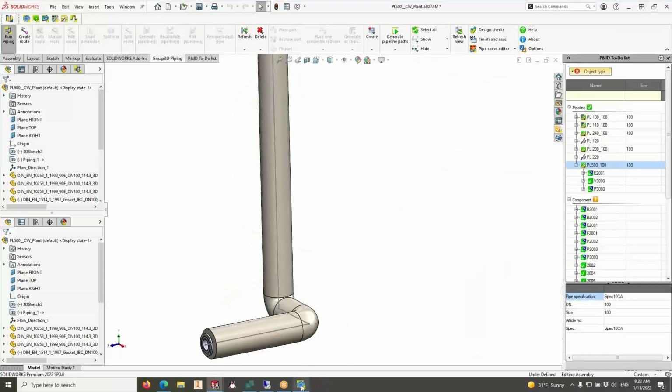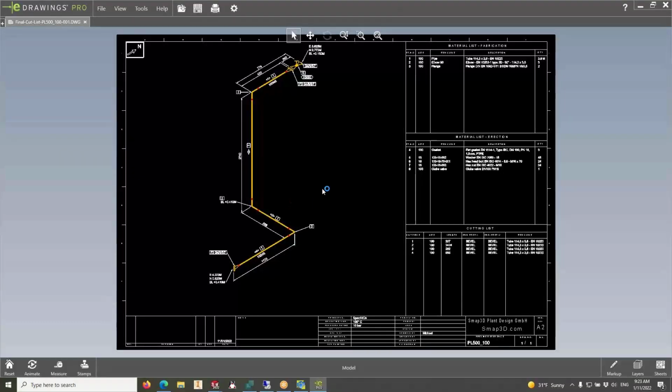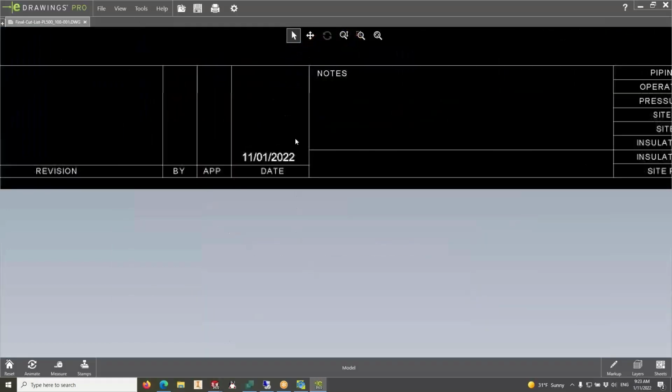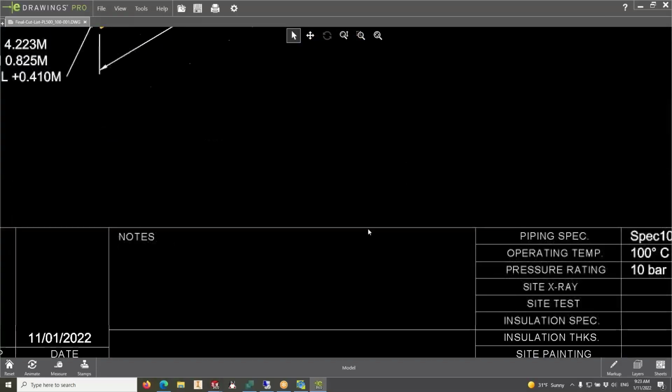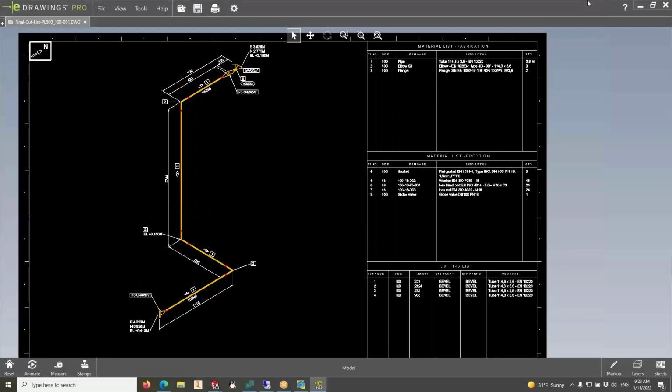And so now we have our nice manufacturing drawing here, ready to be sent out for review or for fabrication. Of course, also you have the DWG. The advantage there is it's a DWG, so if you wanted to go in and put other notes in there, or make a change to it, you could. But typically, I don't like to create extra work for myself, so if I can just get my settings correct inside, I don't have to touch it.